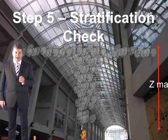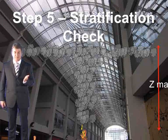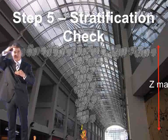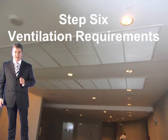Let's move on to step 5 now, the stratification check. Now in this case, because the clear layer height is so low, in other words 3.6 metres, then stratification can be ignored. Stratification only applies to very, very high rises of plume. Not high enough, you don't have to carry out the stratification check. You can move straight on to step 6, which is determining the ventilation requirements.